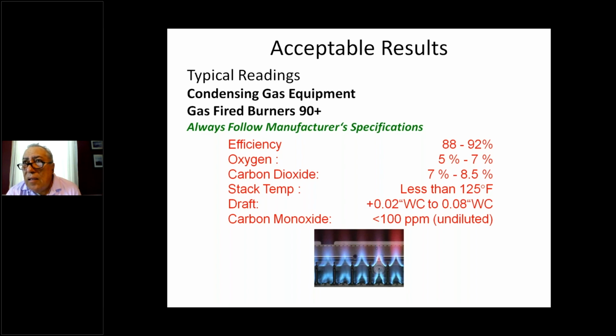Whether it's a chimney or just a draft-induced flow, you're measuring the flow of the flue gas. That's what draft is. And you want to keep it low because we want to keep the flue gas in the appliance as long as possible. So by reducing the draft, we slow it down.